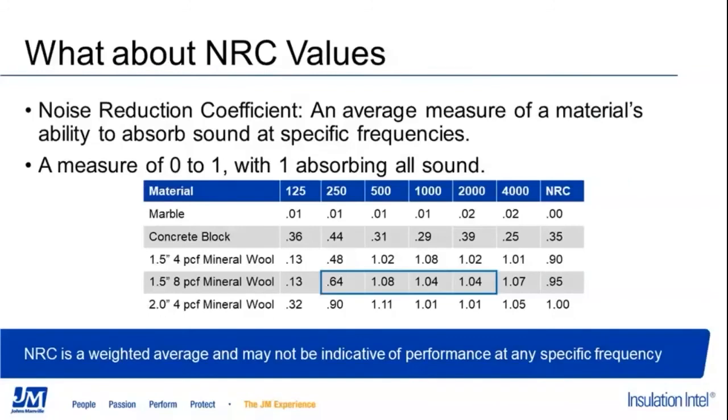Another term that you probably will encounter fairly often is NRC, or noise reduction coefficient. It's important to understand that the NRC is not a directly measured characteristic of a material. It is a calculated characteristic. It is the average of the sound absorption performance of the material at a predefined set of frequencies. And it's a specially weighted mathematical average that then gives you that noise reduction coefficient, or NRC value.